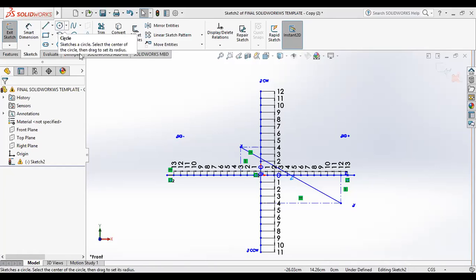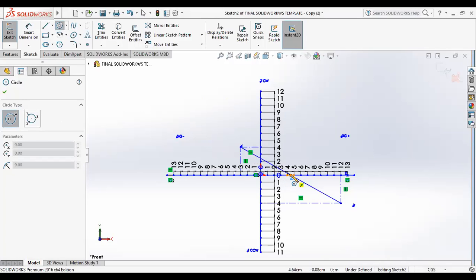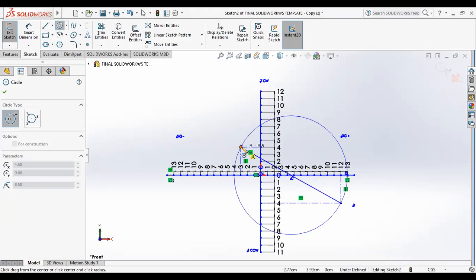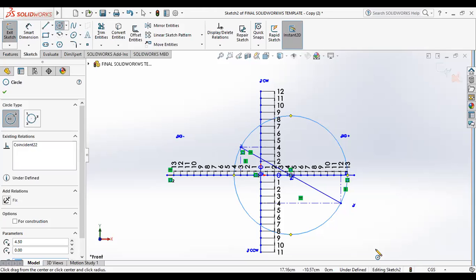Now take this point as a center. Draw a circle, either this as radius or this as radius. Okay. Now, wherever this circle meets the horizontal line, on the horizontal line there is no shear stress.